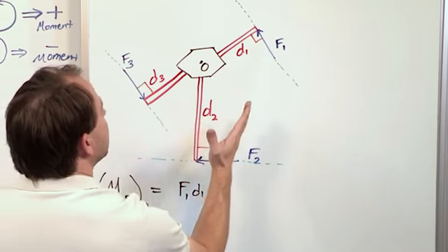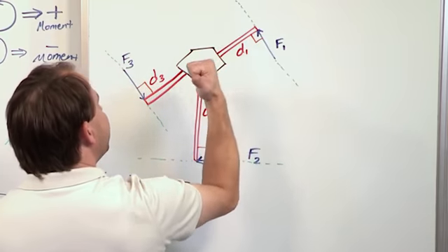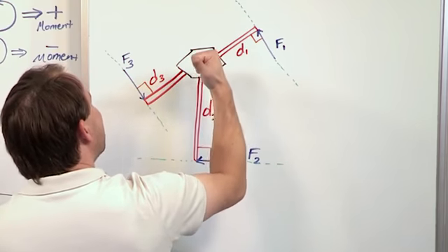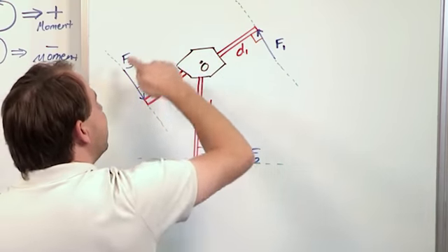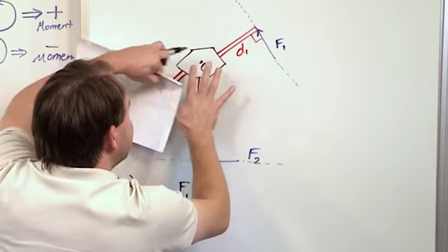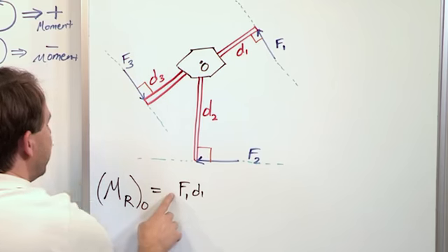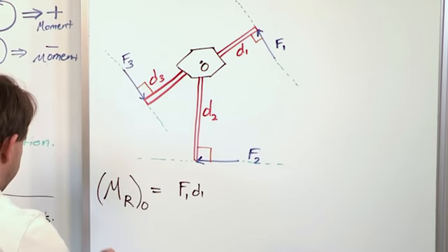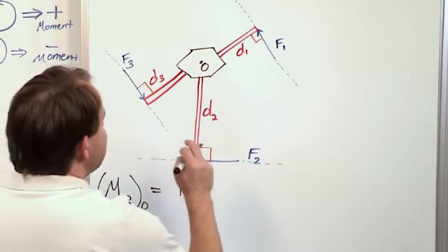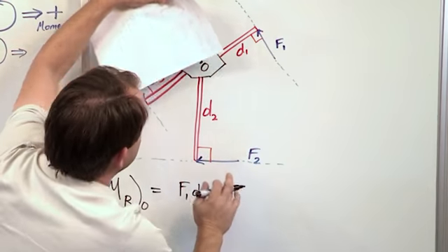The right-hand rule shows it going this way, so if it were represented as a vector, the moment would be coming out of the board, and since this force, forgetting about these, is tending to rotate this guy counterclockwise, we use a positive sign on that, okay? We use a positive sign. Now let's cover everything else up and look at what this one's doing.